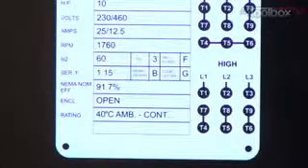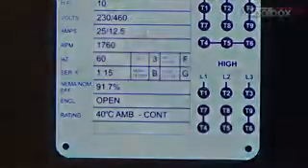There's lots of other kinds of duty motors, like intermittent is a common one. Intermittent motors are designed to be started and stopped all the time. Continuous duty motors are good motors. It's easy to run continuously. It's harder to start and stop a motor. So the intermittent duty motors are built with a little more substantial wiring and things like that.